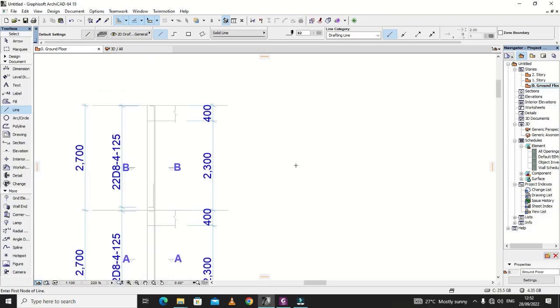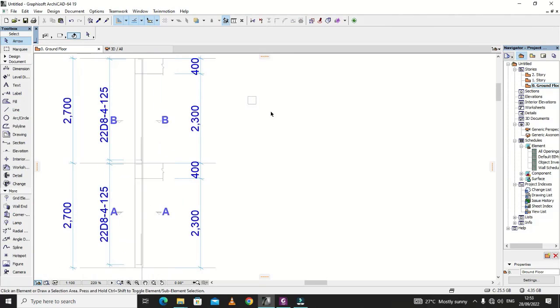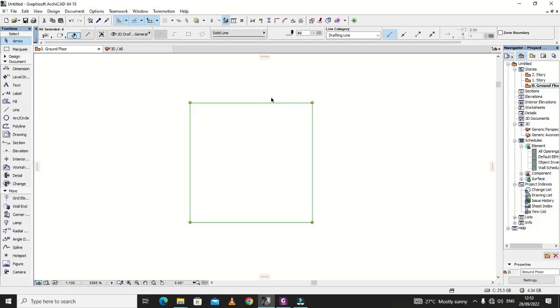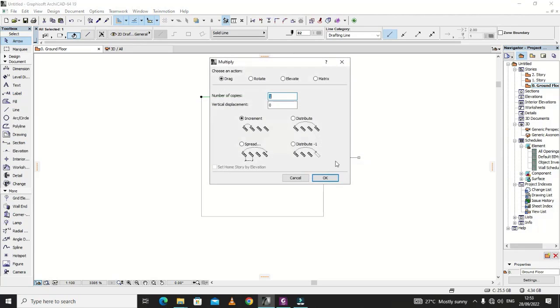So since the base and width of the column was 200 by 200, we shall just select the line and use the box. So we shall start by 200 by 200, like that. Then we shall just draw the section of one side, and then we shall copy the section down here. So we have already created it, and then we can ungroup this. Press Ctrl Shift G, press Ctrl Shift G, and then just mirror all these parts inside.